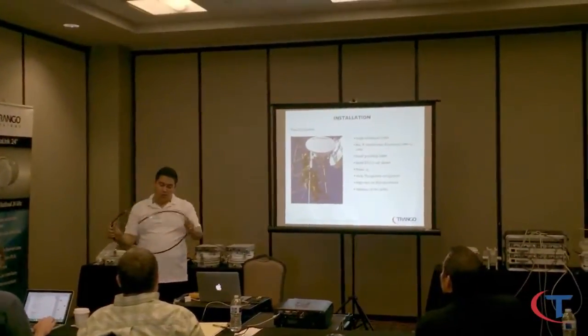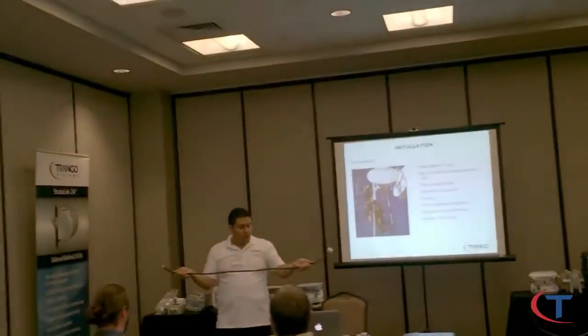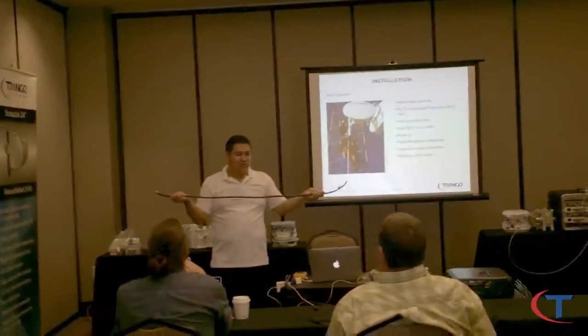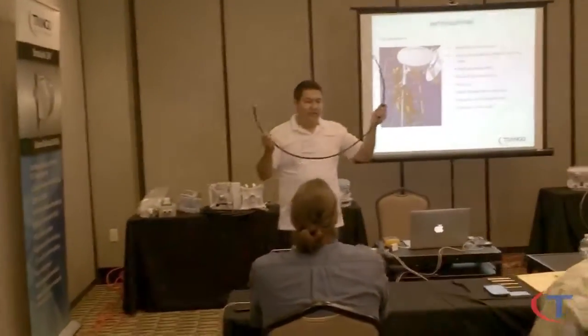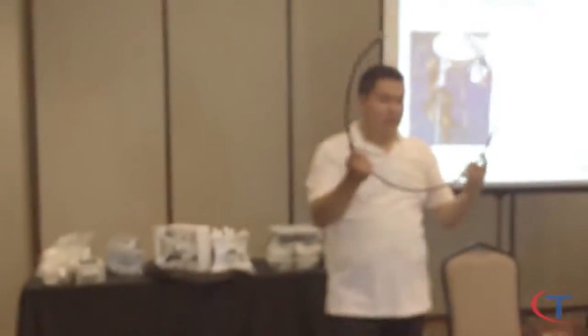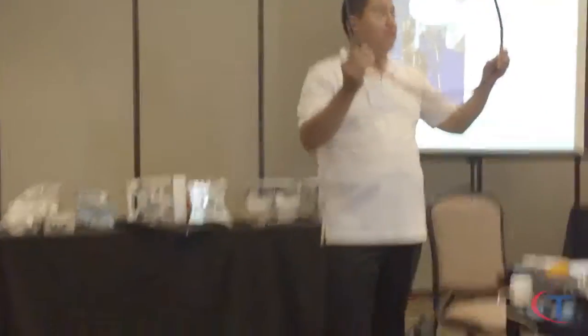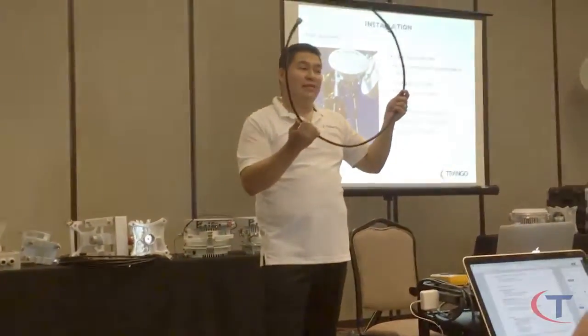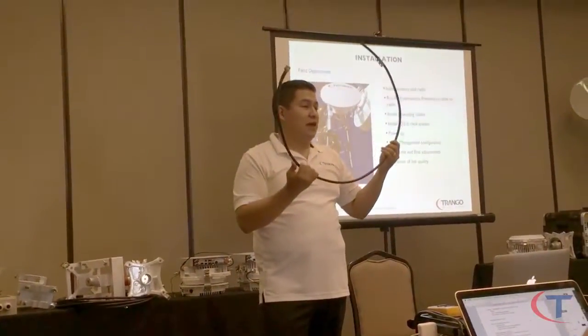If it's a U, that's fine. You don't want to do L, 90-degree corners, from this, okay? That's going to make a really nice short on the actual cable. So anything about like that is fine, but you do not want to do a 90-degree bend on this. This is not designed for that.